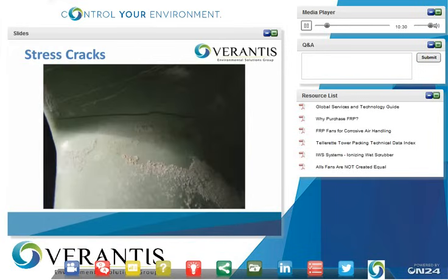This photo shows buildup. Buildup, if it remains uniform and doesn't come off in large chunks and pieces, really doesn't affect your vibration levels too much. But when you have material starting to come off and the fan goes out of balance, you reach a certain point where the fan is seeing stresses and forces that it's not normally meant to see, and you'll start seeing fatigue cracking. Cracking is no different than taking a thin piece of steel, flexing it multiple times, and eventually it's going to crack. Fiberglass does the same thing.